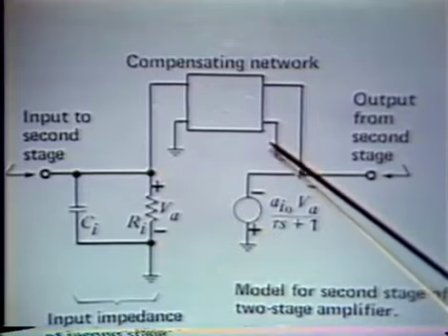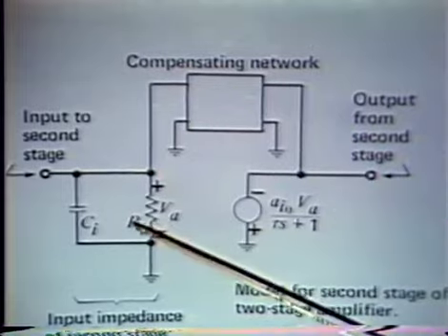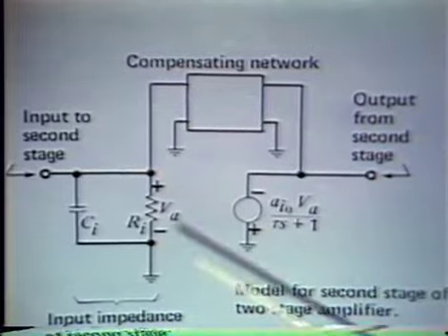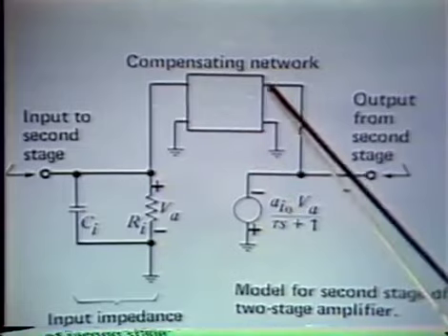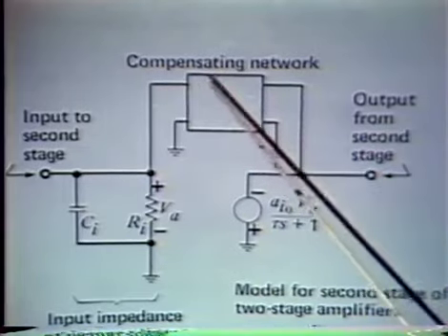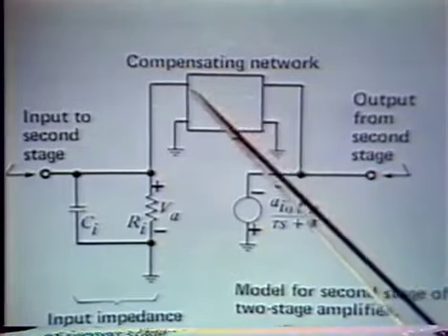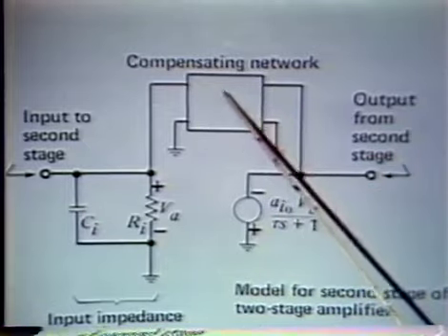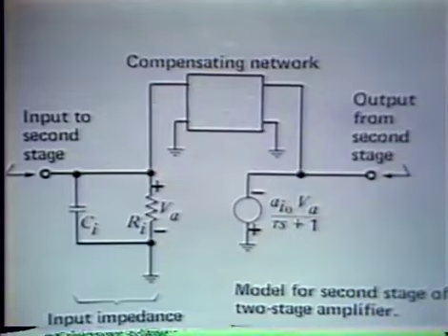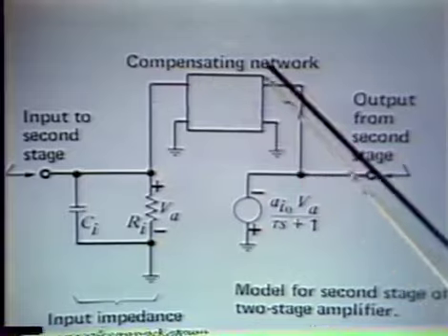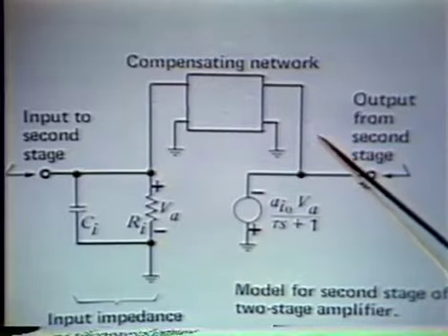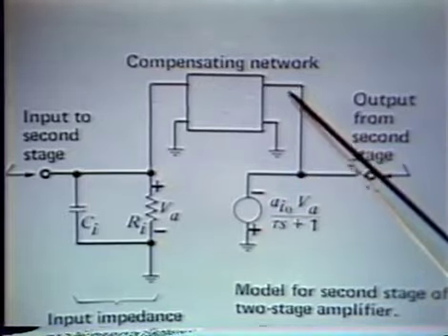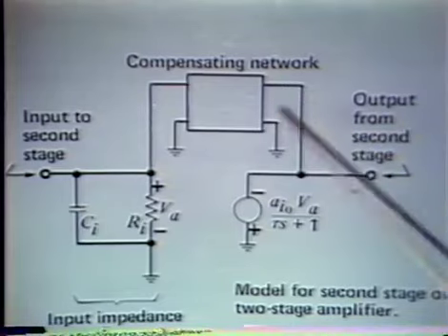Well, if at crossover in the minor loop, this network looks principally capacitive from here to here. In other words, if it looks like a single capacitor, or if it looks like a T that has two capacitors across the top and a single resistor down on the vertical portion of the T. Then at high frequencies, we get simply an attenuation between this voltage and this one.